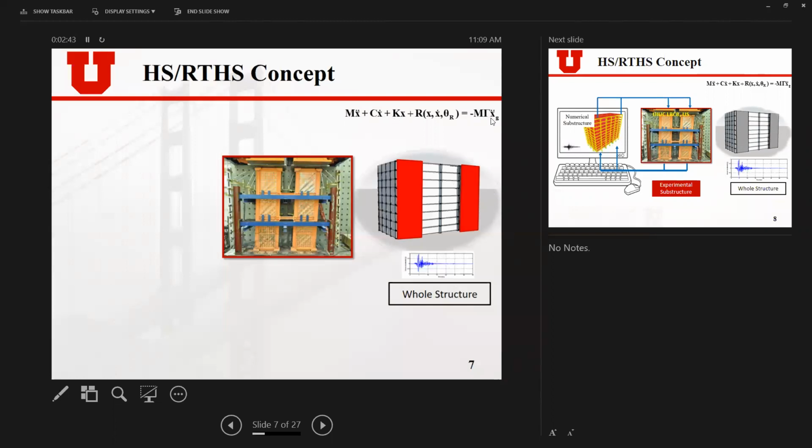If we choose to investigate both the component performance and the performance of the structure with this component in it, then we can use a hybrid simulation, still choosing only the shear wall as the component to test, the same as the setup in the quasi-static test.